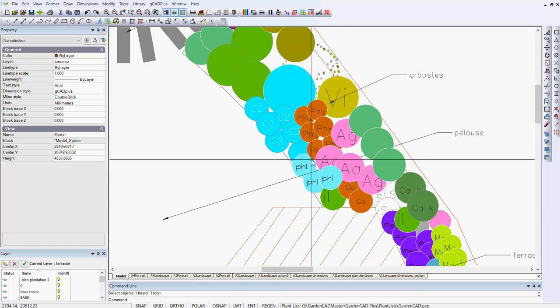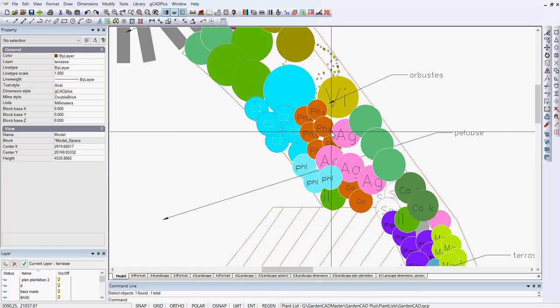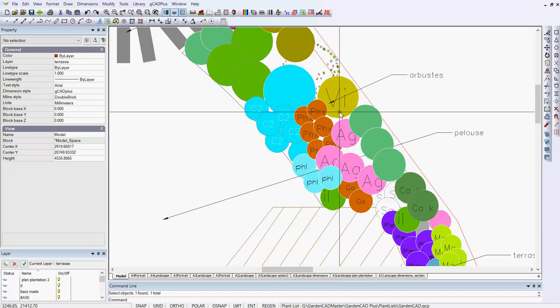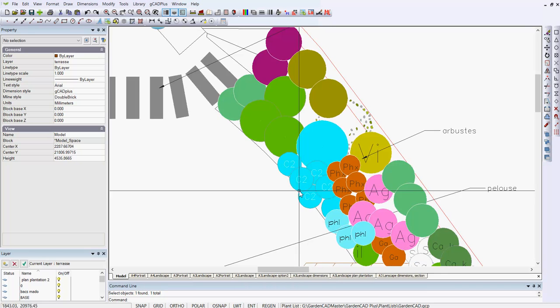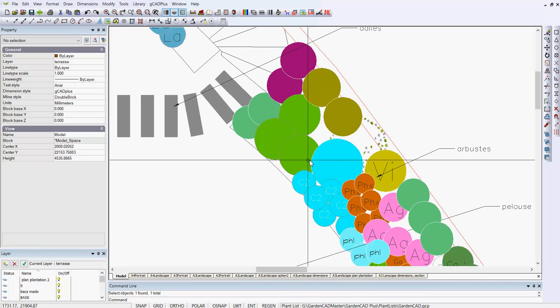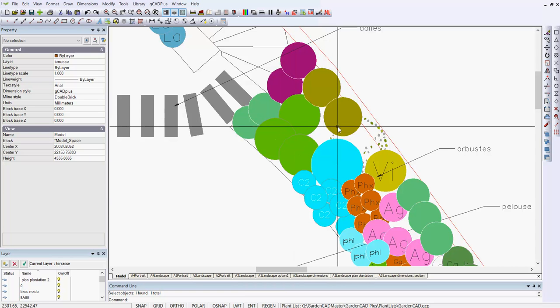While that works fine, what it does do is give a different height of text in each symbol. So if a symbol is scaled differentially, then the height will scale with it. So there is a better way to apply a label to those symbols and to have the label, the text, the same height, which leads to a clearer impression.